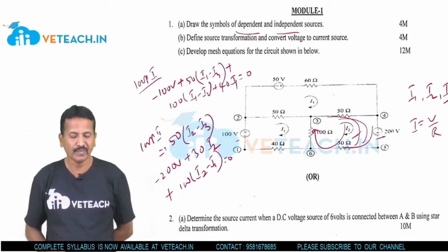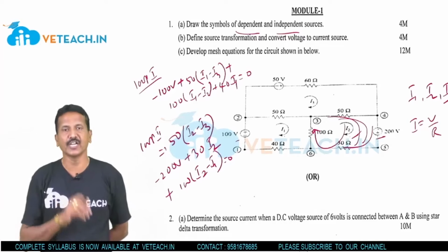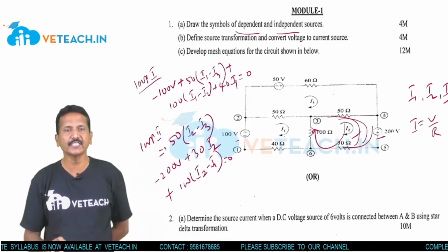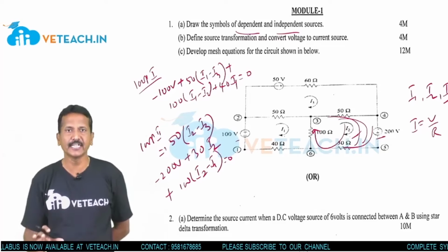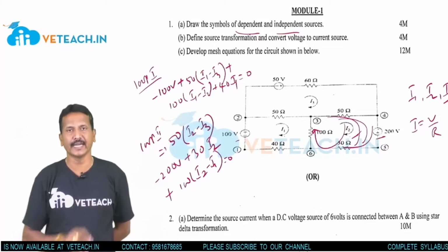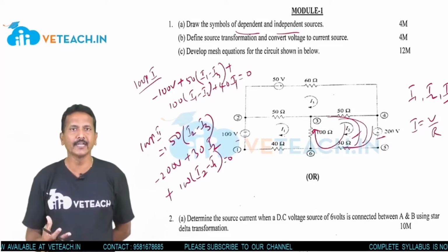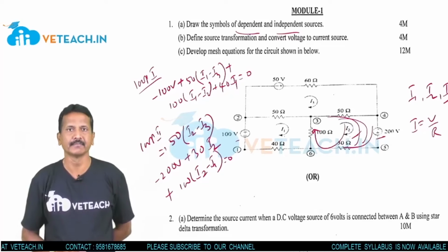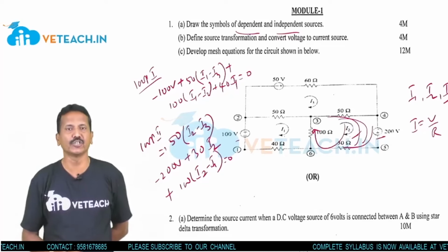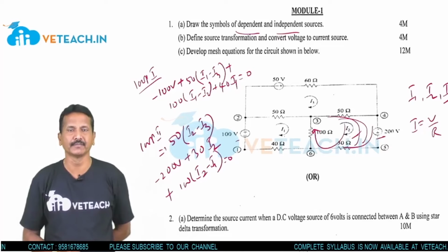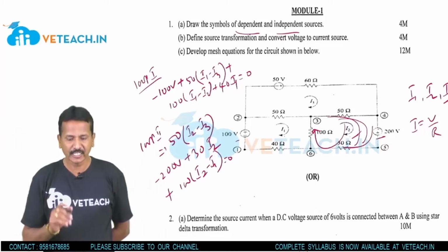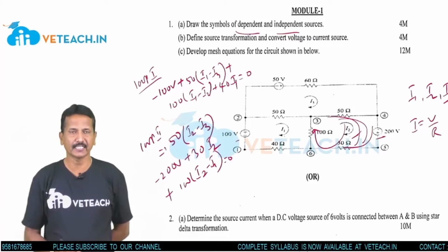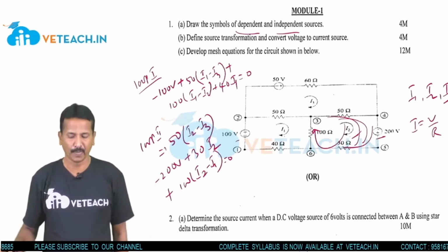This is the basic concept of mesh analysis: closed path, current is flowing across each and every branch, write the relations, equalize them and find the unknown currents. You know current, you know resistance, can't you find the voltage? Yes, it is nothing but the voltage drop across each and every branch. Such types of problems are very, very important, students. Practice as many problems as possible.